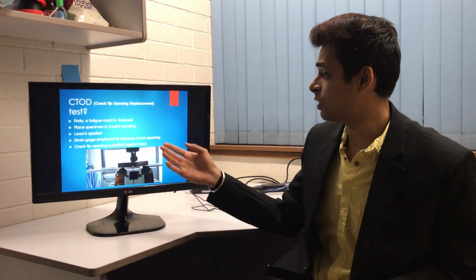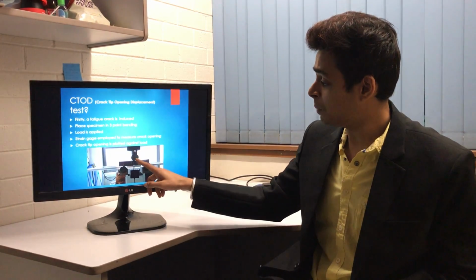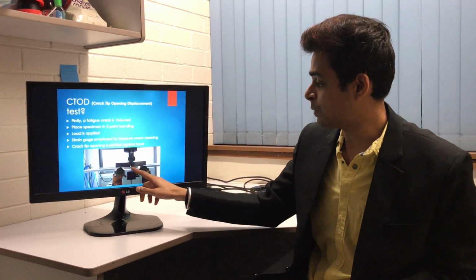Firstly, we take a specimen which we need to measure or test. A crack is induced in the center of the specimen first, and then it is placed between the 3-point bending apparatus that is shown over here. Now the center point over here is used for loading. It gives a constant loading for a long time, and the crack keeps opening and opening till the specimen actually